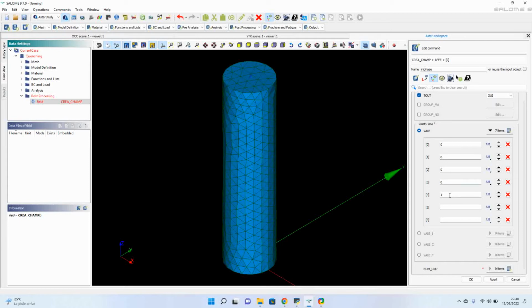And in a Jominy quenching test, since we are starting with a purely austenitic structure, we won't use that field. If I remember correctly, it's related to the martensite temperature or something like that, but I never used that field. And the last one we have to specify is for the grain size.